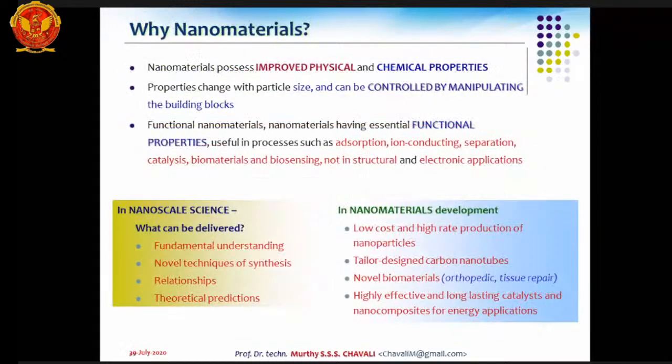And why do we use nanomaterials for sensing? Because they have simply improved physical and chemical properties. And if you use some dopants and change the architecture or layout, that itself can act as a sensor. For example, if you take a single-wall nanotube or multi-wall nanotube, just entwining them can change the resistance or conductivity within the tube. That itself triggers the difference between before and after contact with the gas, and so on. It can act as a sensor.